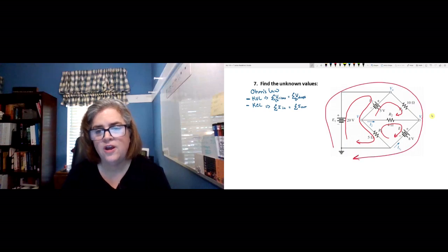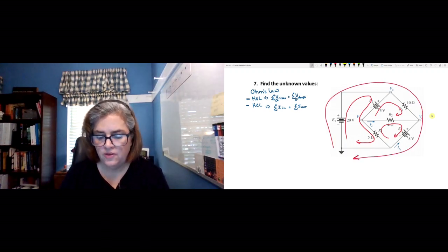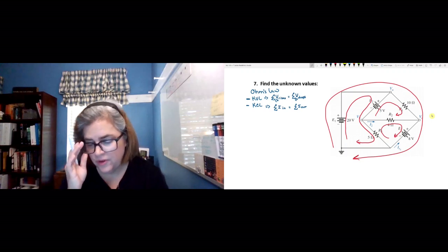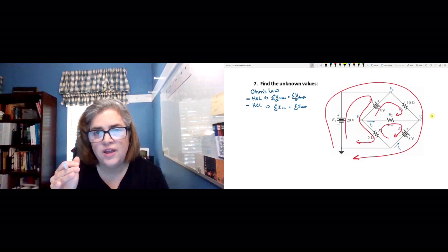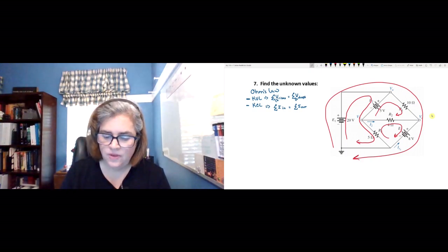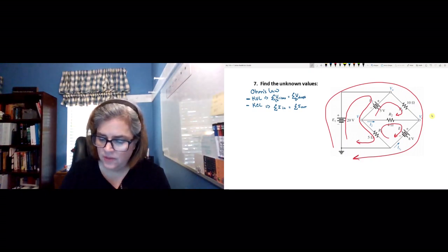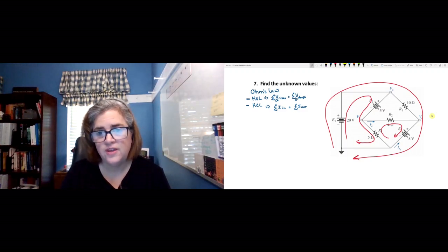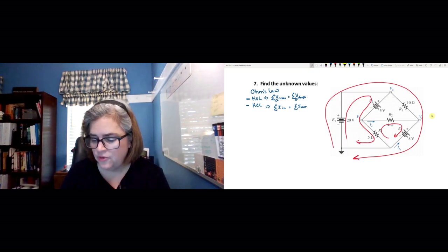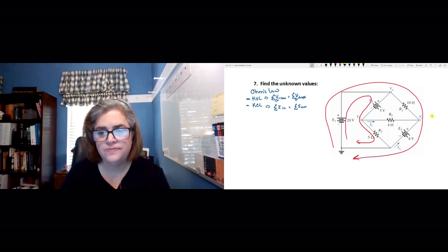So there's a few different opportunities for us to write voltage law equations here. It doesn't really matter where we start as long as we start in a place where we don't have too many unknowns. So for instance, I'm going to remove this because two of those three voltages in that group we don't know. We only know the one that's source E2. And two of our drops here we don't know.